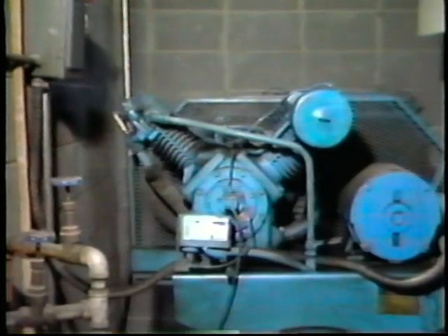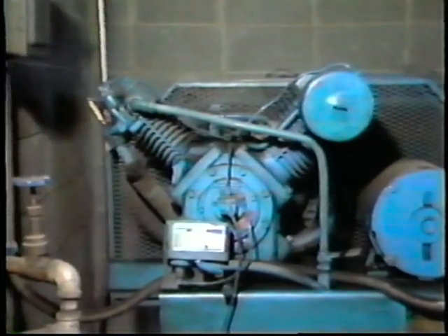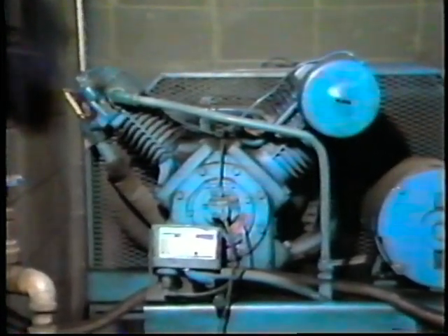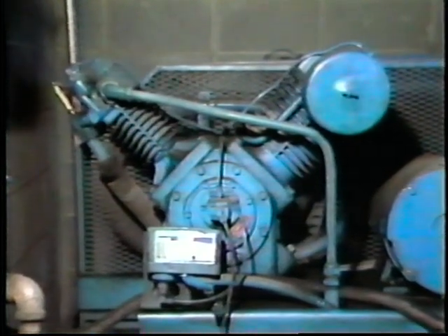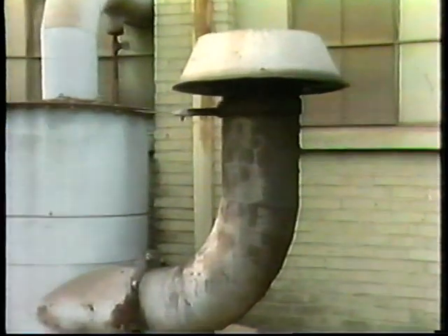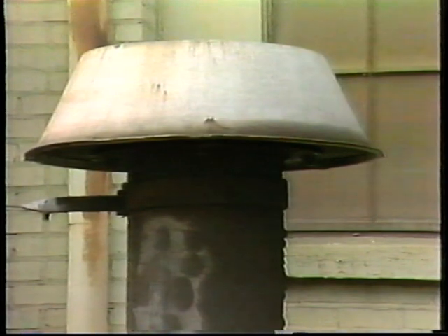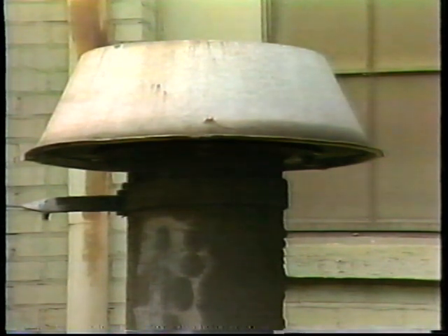Here are some other tips when you're planning a new system or making changes to an existing one. First, try to get the compressors as close as possible to the point of use. Savings will be in shorter supply lines and lower pressure drops. Remember, your compressor likes cool, clean, dry air, so keep air intakes away from dusty yards, parking lots, or smokestacks that might contain contaminants which can damage the compressor.